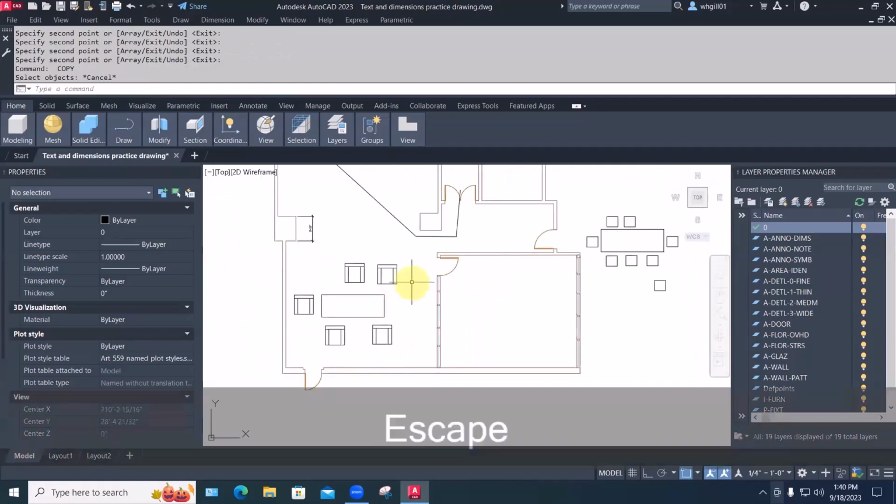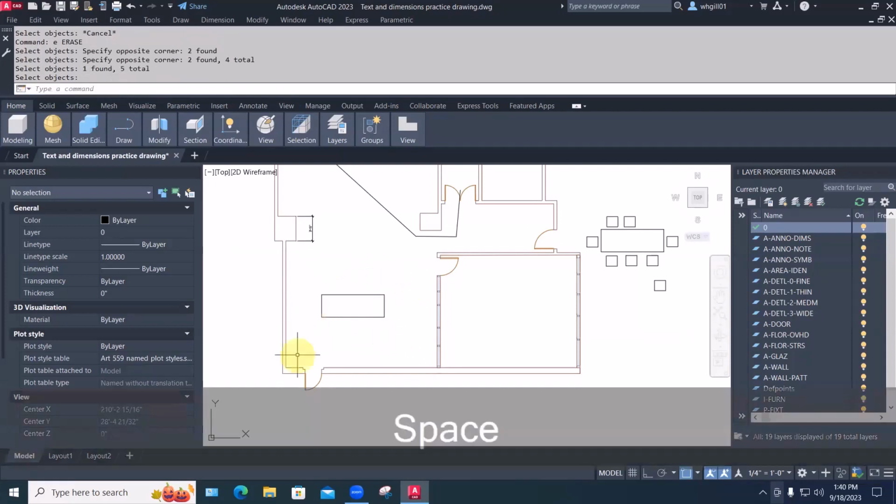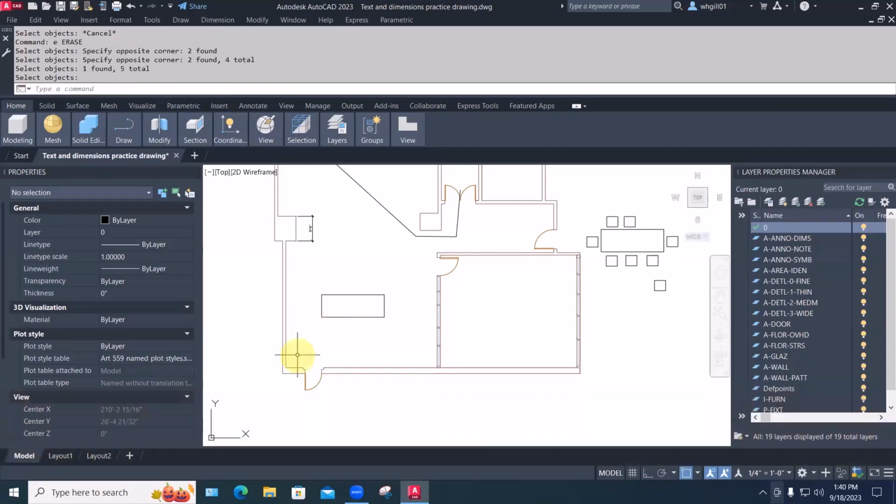Or even if we erased all these, we have created in the drawing's internal database the idea of that chair, Easy Chair 01, as a block. It's a known thing in this drawing, even if it doesn't appear on the screen. So we can bring that up a couple of different ways.